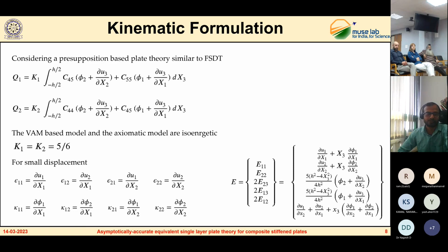Right. So one is the advantage you get in terms of implementation. The other is the very philosophy involved, because right from Berdichevsky, Professor Hodges, and the entire community associated with VAM, we have taken dignity in the fact that we have minimized the ad hoc assumptions, if not completely eliminated them. When you have an asymptotically correct theory, there is no point in trying to curve it into a Timoshenko model for beams, or a Reissner-Mindlin kind of model for plates or shells. It's like working around to touch your nose all the way instead of touching it directly. So I think these are all huge advantages.